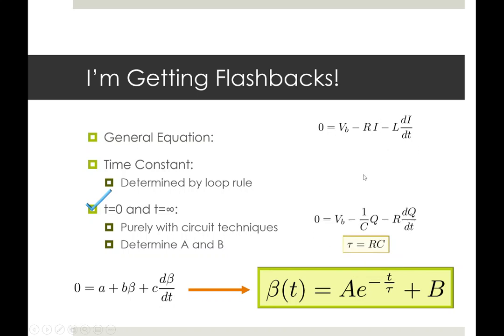And let me sort of draw the analogy. This was the loop rule back from the RC circuit that gave us a time constant of R times C. And here you can sort of see, we can draw down all the analogies: I can plug in R for 1 over C, or maybe 1 over R, and then L takes the place of R. If I sort of put that analogy together, I get actually the right answer. Now, of course, you would get this by doing the full differential equations analysis, but I've just sort of skipped and connected the dots here and said, this does actually work to sort of draw analogies and find a time constant of L over R.